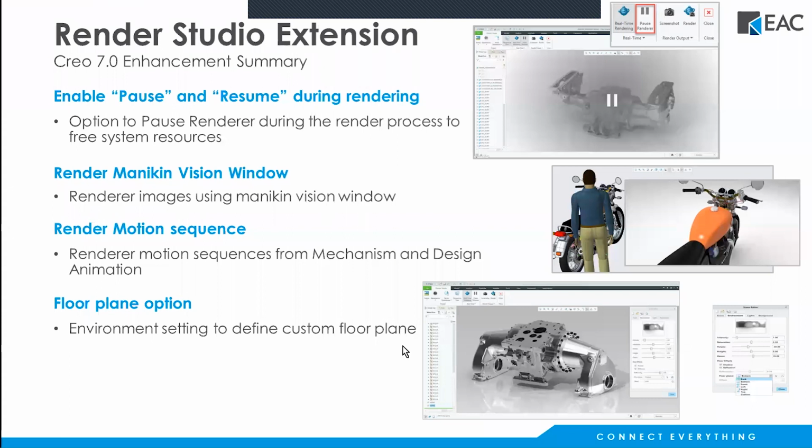Another thing that was added is that by default, KeyShot would just put your part on the floor, and then it would shade it. So you'd have reflections like you see in this guy down here. Now there's the option, you can go under the environment and settings and say the floor, I can pick another plane to be the floor, or I can offset the floor. Basically what it can do is make your part look like it's floating in space and not necessarily sitting on top of something. And maybe the reason you're doing that is you're making a parts catalog or something. You just want the image of the part there, and you don't need to have it sitting on a table or anything like that. The focus is really the part itself. So that's just another thing you can do, to lower that floor or get rid of it, so your part's just sitting there in space.